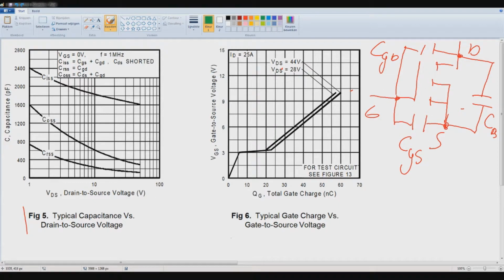As you can see, there's a little bit of difference which you must keep in mind. Perhaps it's a little bit linear. Yes, it is linear. Therefore you can estimate, for example at 12 volts, that it's about like this. Maybe it's not so true, then you must create a test circuit, which we can see later. But let's take a look at the total gate charge in nanocoulombs.